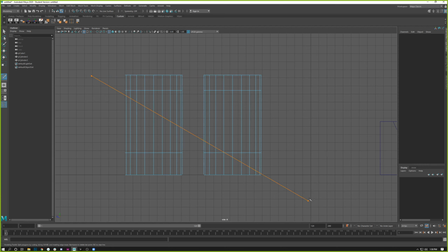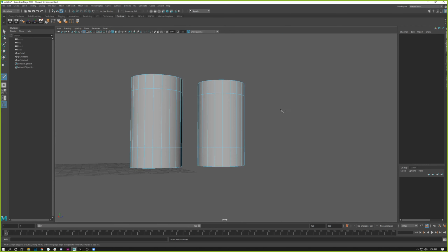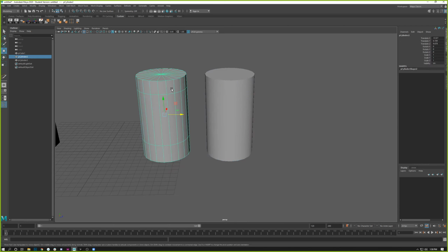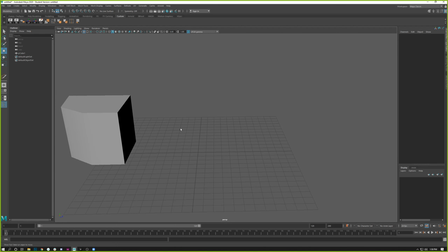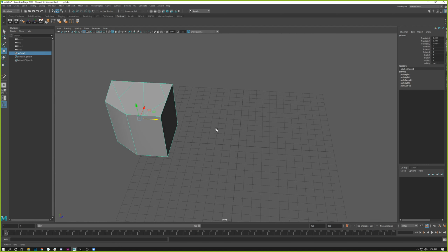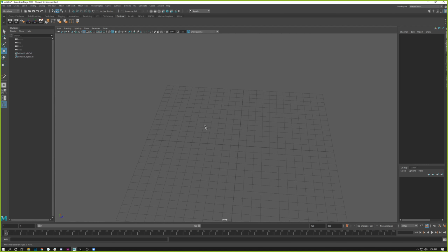You can change the increment that it snaps. So right now it's in 15-degree increments. And you can see cuts. So there's a lot of things you can do with just this one tool. Definitely one of my favorites in there. Heavily used in modeling, and you can do a lot with it.